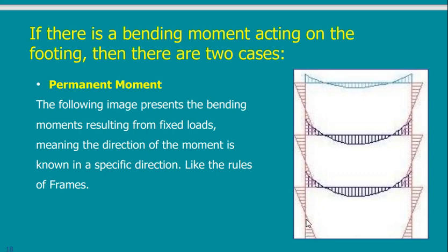Suppose I have from the column a normal force. Yani this frame has two things. It has a moment here, and of course it has a normal force. Take this moment, divide it by the normal force, you will get an eccentricity, a value of a distance. If you manage to shift the column in a direction opposite to the moment, you will induce another moment that is equal to the original moment, but opposite in direction. You understood what I mean?